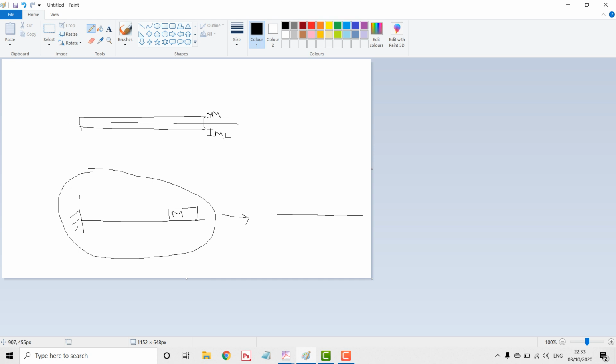the beam with various different elements, each with two nodes, like a connection of various elements. And then I am arresting this node, setting all the translations to 0 and all the rotations to 0. Each node point in the FEM has 6 degrees of freedom: 3 translations along x, y, and z, and rotations about x, y, and z. So all 6 degrees of freedom will be arrested since it is clamped.